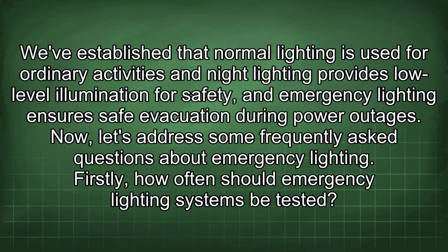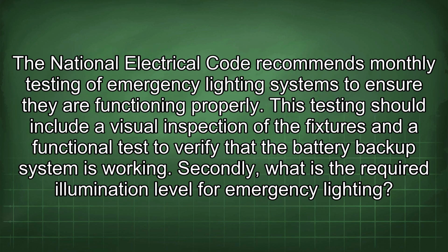Firstly, how often should emergency lighting systems be tested? The National Electrical Code recommends monthly testing of emergency lighting systems to ensure they are functioning properly. This testing should include a visual inspection of the fixtures and a functional test to verify that the battery backup system is working.